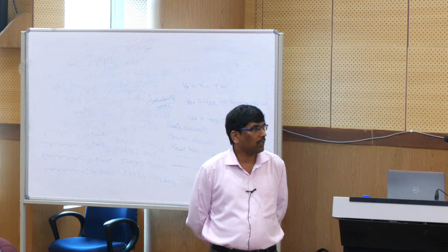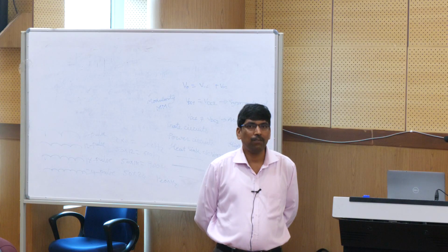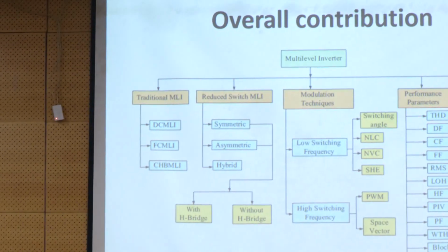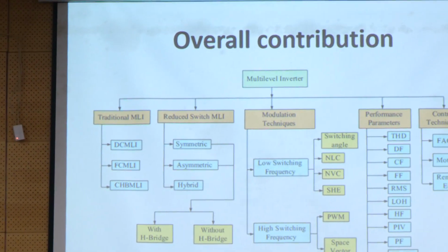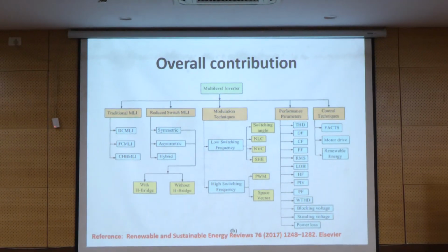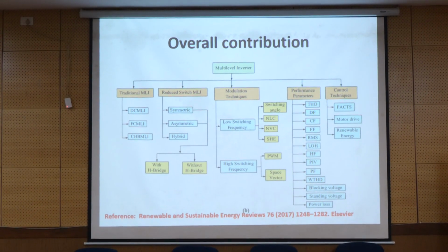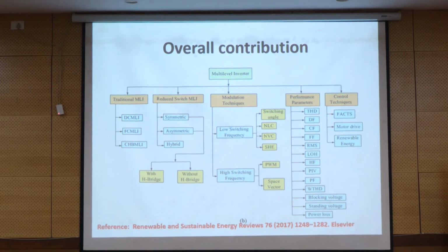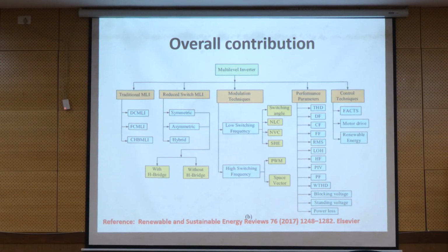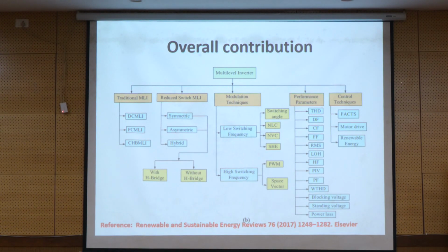So, if you have the switching frequency higher or lower, what matters? Higher or lower? Yes, losses. If you make use of a higher switching frequency, then the losses are going to be higher, and if the switching frequency is lower, the losses are going to be lower. So how is this loss going to be calculated?